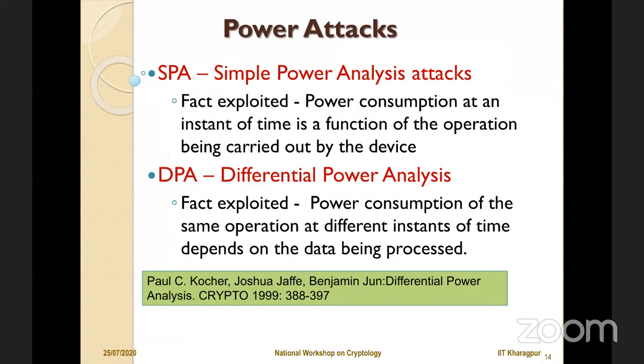So power attacks typically are of 2 types. The simple technique is what is called simple power analysis, or SPA. And there is another technique which is more sophisticated, called the differential power attack, or DPA. In a simple power attack, the fact which is exploited is that the power consumption at an instance of time is a function of the operation being carried out by the device.